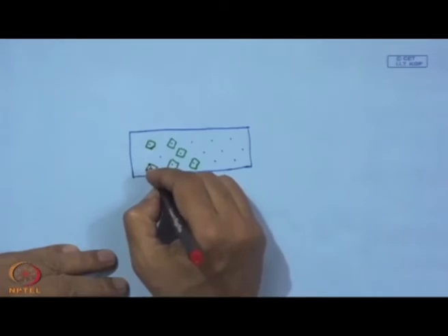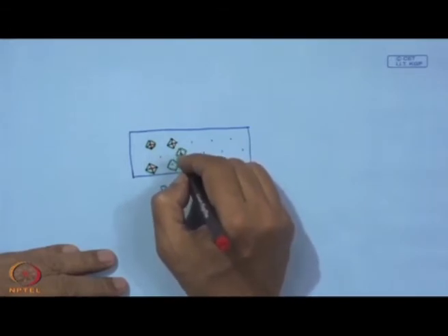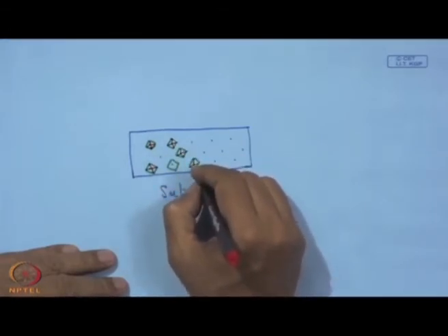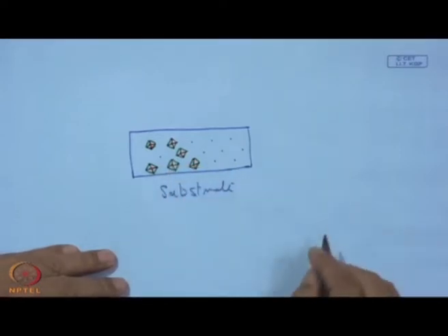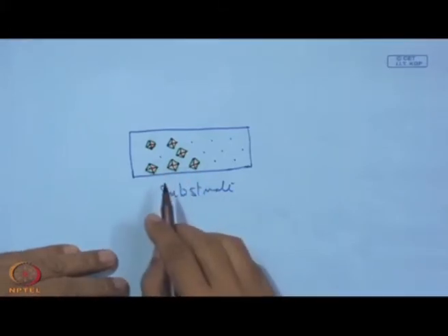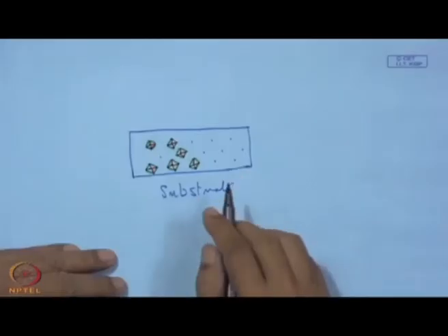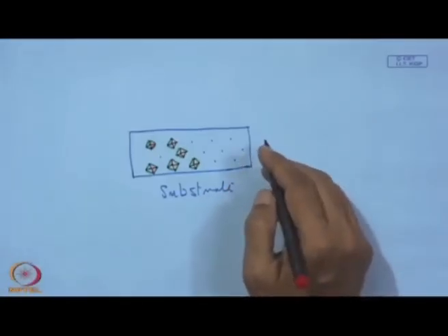So, this is going to be one diamond site, and these are not just a diamond coating, but crystals individually grown just like this crystal, and this will become self bonded. We do not need any bonding material, neither braze alloy nor galvanic nickel. It is just on the substrate surface. Now, for this substrate surface, its chemistry is very important, because it should be bonded automatically by natural bonding.